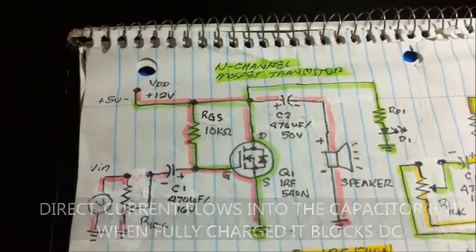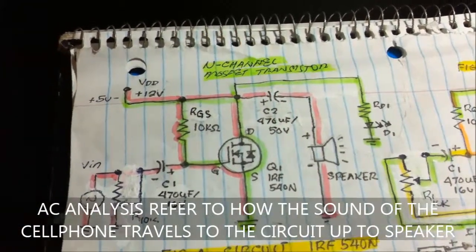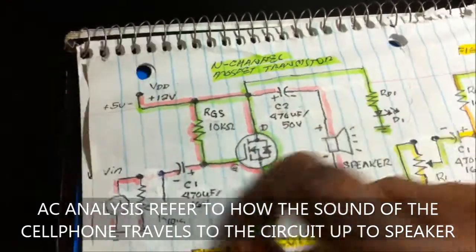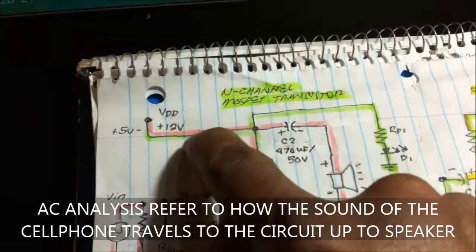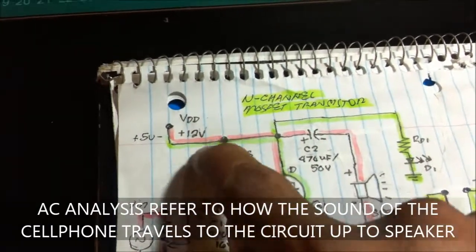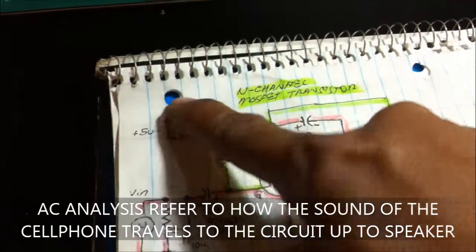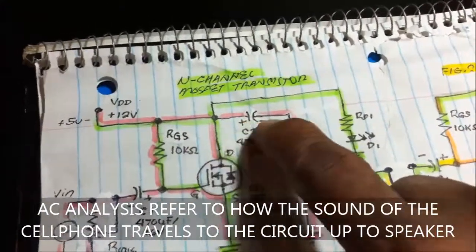How about the AC? We have two components of signal here or current flow. The AC signal from the audio source or from the cell phone flows by using this red line here into the gate, to the source, to the ground, to the resistor, up to the 12 volts. When AC is coming here, it seems like the 12 volts is grounded. The AC sees the 12 volt supply as ground, so it is ground. Also flows here to the drain, to the source again, and to the capacitor.